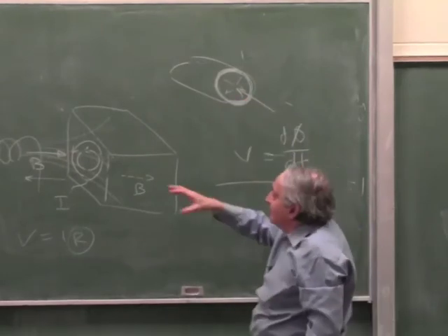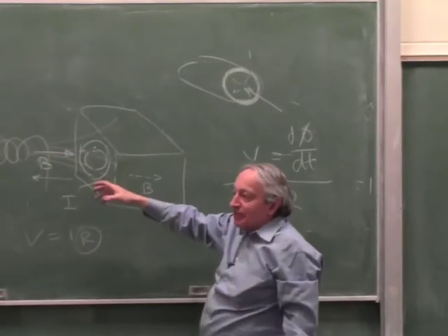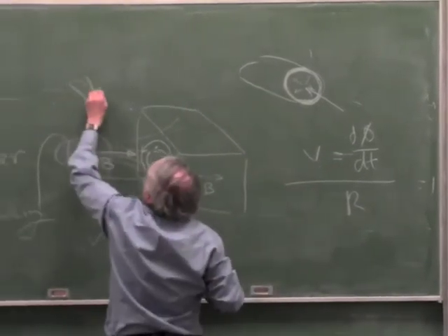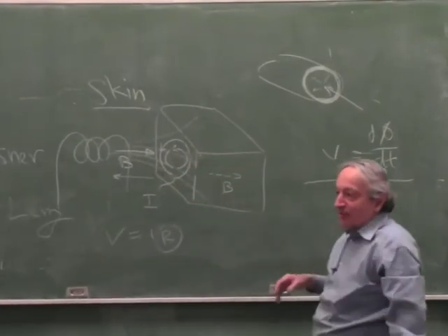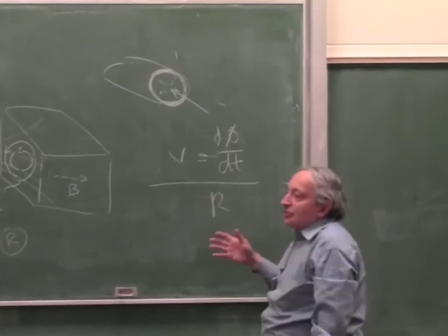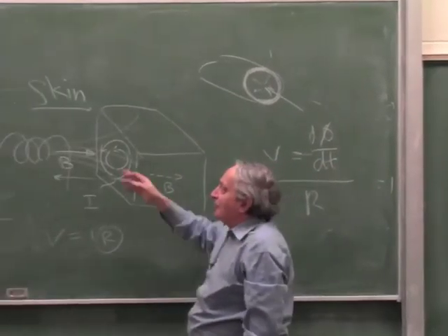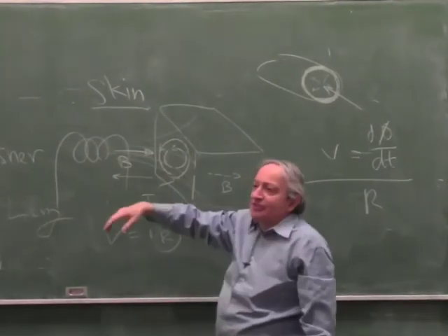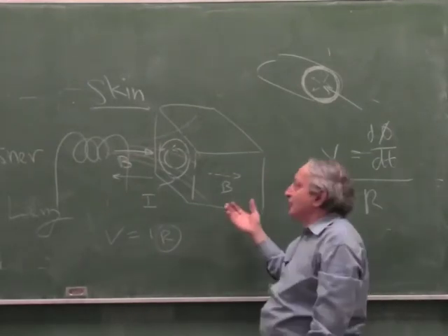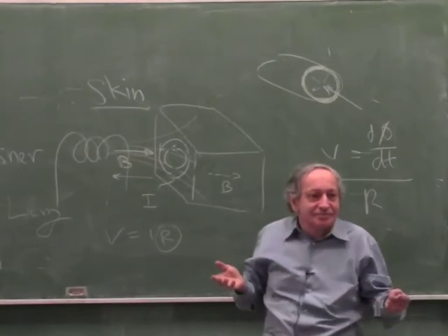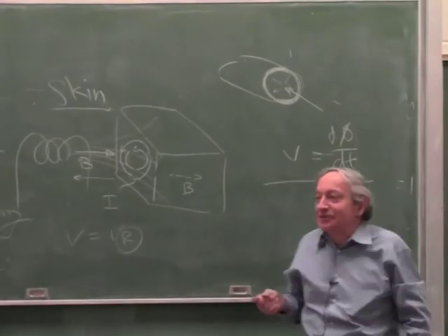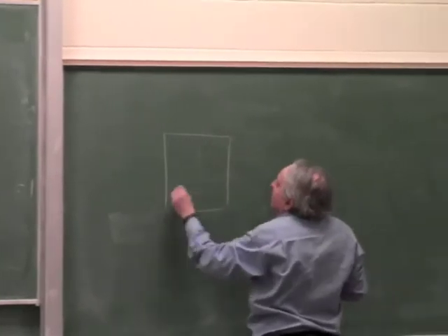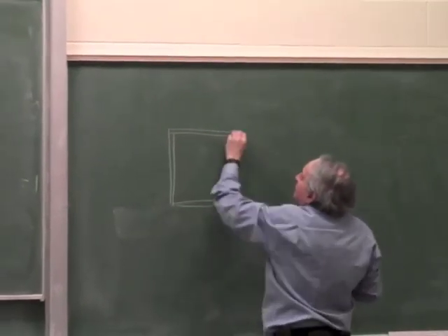So the reason why the shielding at high frequency is bad is that the steel appears much more resistive than it really is at high frequency because of skin effect. Skin is like human skin, it's not the name of a person, right? Okay, good. So what do you do if iron is bad for skin effect, because in ferromagnetic materials the skin depth is much less? If iron is bad for skin effect, and copper is bad at low frequency, what should you make the box of? Of what? Both. Exactly right, both. Since we can decide, make it from both. That's why for high shielding you typically have a steel box coated with copper foil.